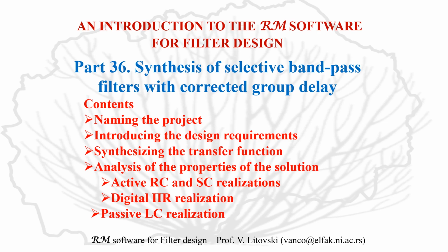We will go first for the naming of the project, then we will introduce the design requirements, then we will perform synthesis of the transfer function and analysis of the properties of the solution, and then we will take two paths for the physical system realization. The first one goes for active, which means active RC, active SC, and digital infinite impulse response realization. And the second path goes for passive LC realization.